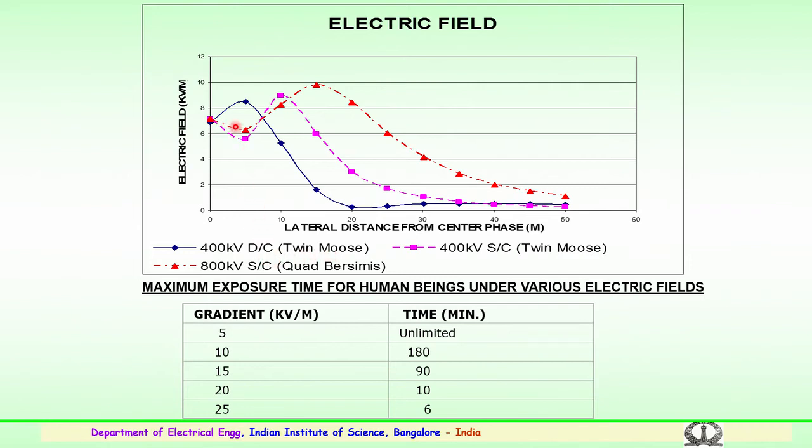The noise generated over a period is shown as follows, depending upon the distance from the tower. So, 0 corresponds to the height where the conductor is being used, then the field shows high very near to the conductor, and towards the ground end, the electric field decreases. That is how the field decreases over the ground level from the tower side. Similarly, you have a red color with triangular markers for 800 kV single circuit, a similar type of scene.